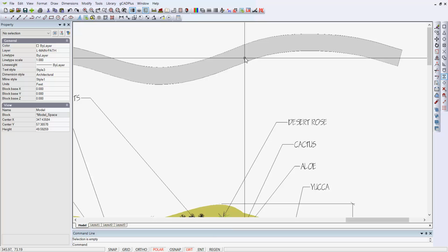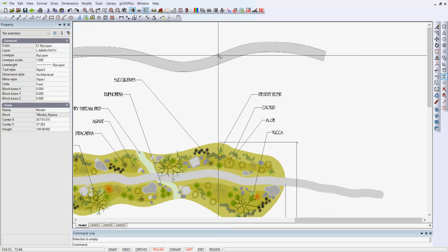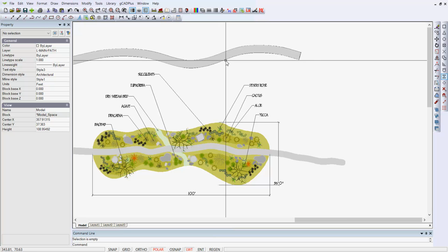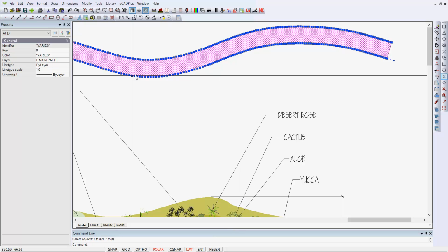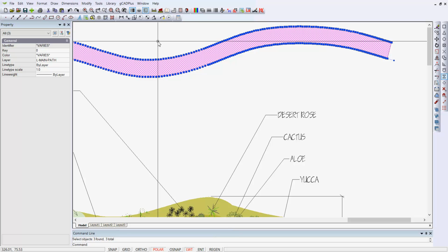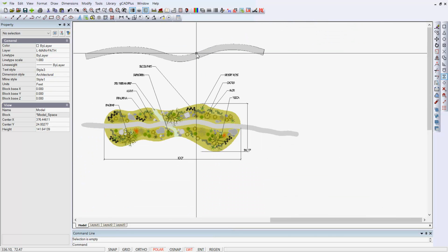You might dislike that sort of edge to it, but I'm relatively happy. You can select. We have a number of things in here. In the list we've got the polyline and the hatch itself. So you could actually change the layer of the polyline or change its colour, and that slight fuzzy edge to it would disappear.